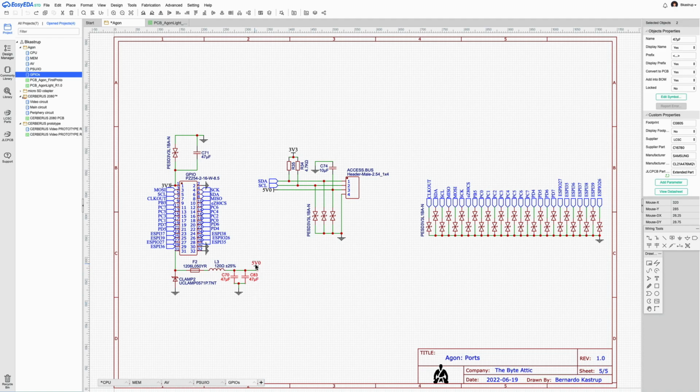But now it's for the 5 volt line, because the 5 volt pin 31 here on this connector, the control connector, can also be used to power an external circuit. And therefore, these two decoupling capacitors ensure a stable power level.